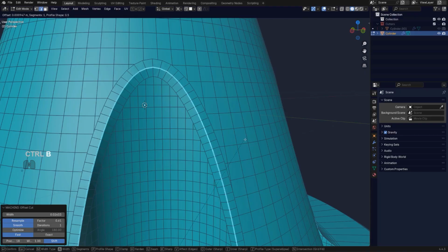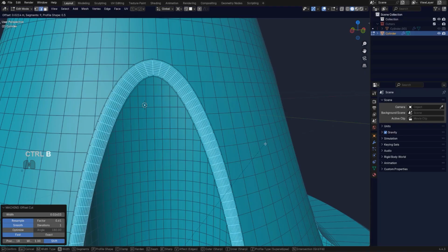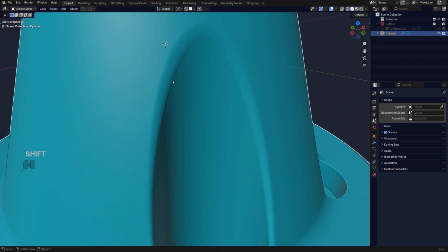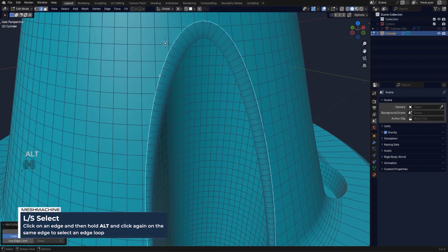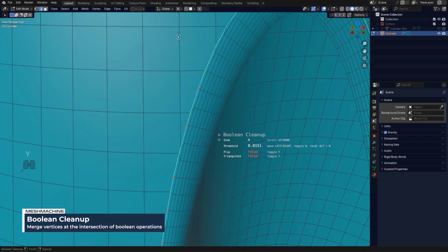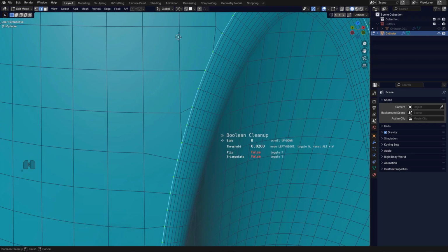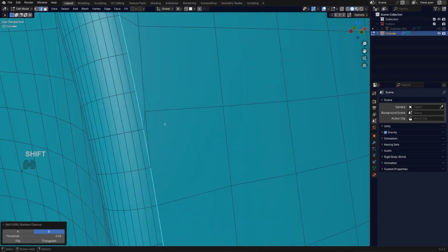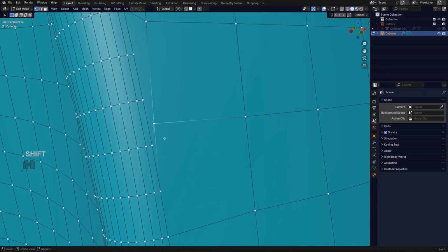And then we can run the bevel on it, it's okay. So let's run the bevel on it. How are we looking? We're looking good. And then Alt click on this one, and we can clean up this nonsense. So boolean cleanup with your mouse, scroll it up, so you can switch to the outer layer, because scrolling the mouse you can switch between sides, yeah. And scroll until you see all these squares being highlighted and all the reds being gone, which should fix all the issues.